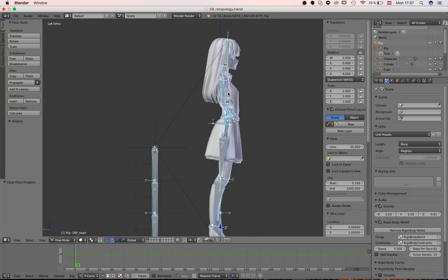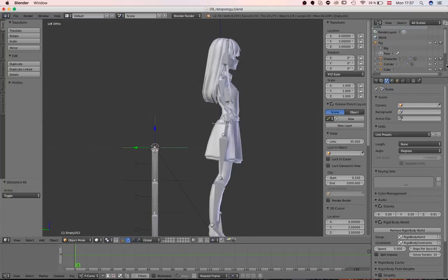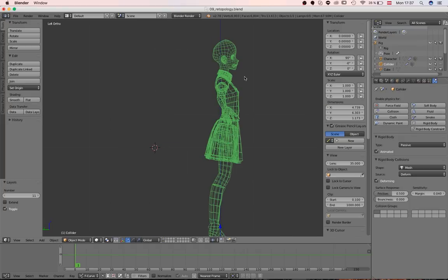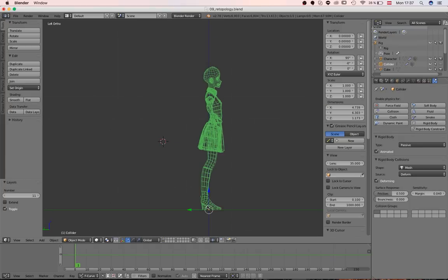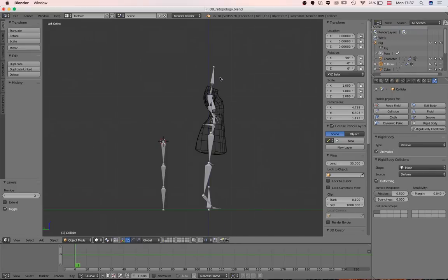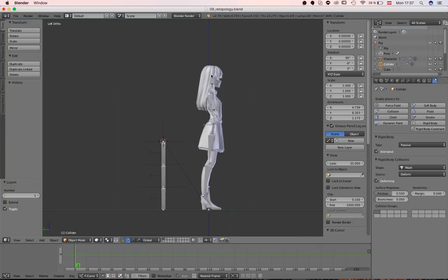and reset the rotation. Basically, the issue is that our first rigid body constraint connects the first cube to the collider object here. The problem is that the collider object itself does not move when the head bone moves. We need an object that is only parented to the bone itself, that is used as a connection